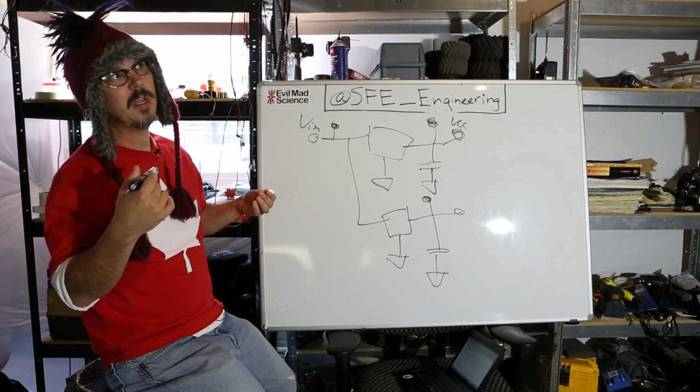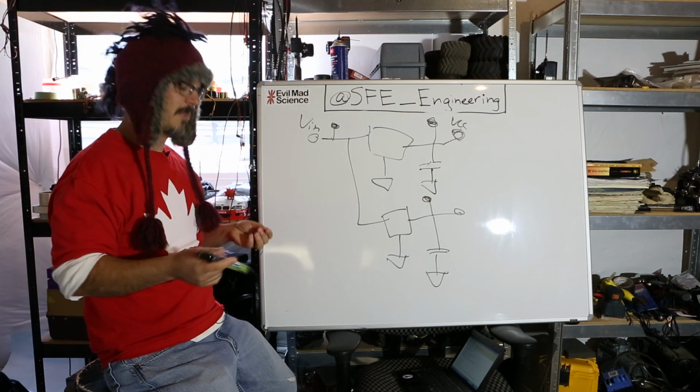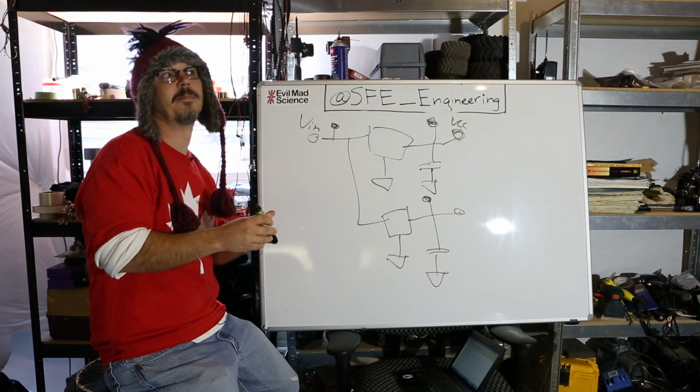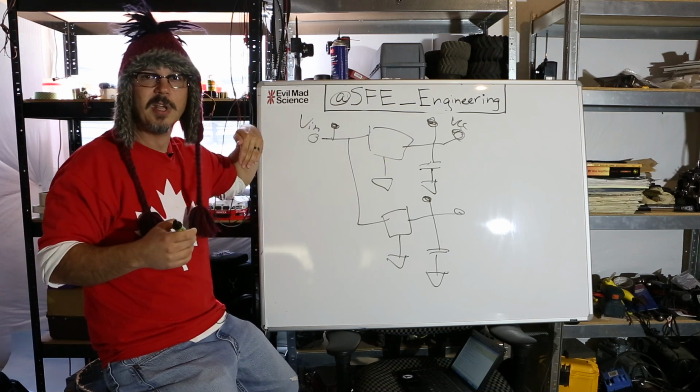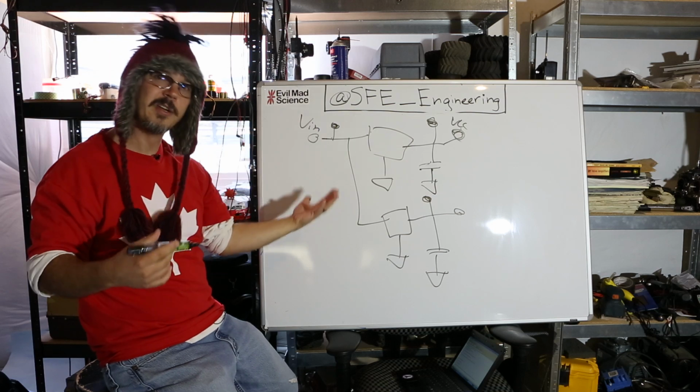You might want to know the output state of an op amp, because that will either tell you if the op amp's bad, or if something in the previous stage is bad, or your biasing resistors are not well adhered to the board.